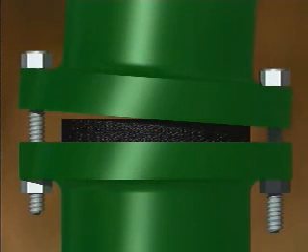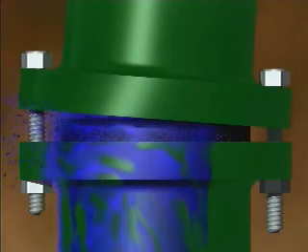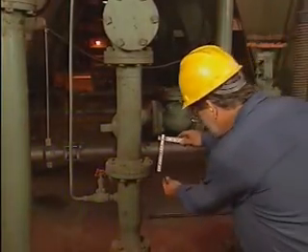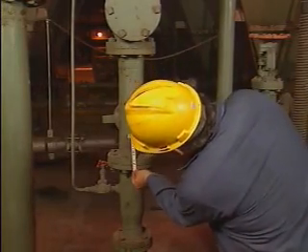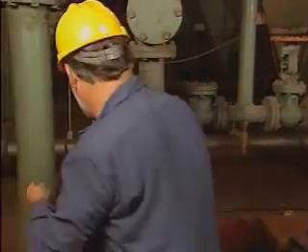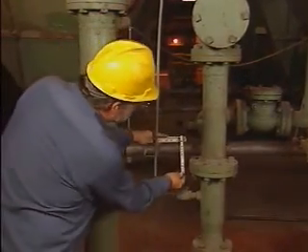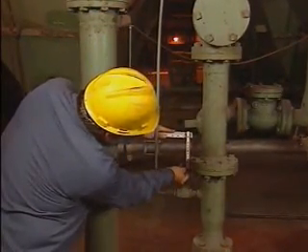If the flanges are out of alignment or the sealing surfaces are not evenly machined, the sealing surfaces may not be parallel. If the sealing surfaces are not parallel, the gasket material may not compress properly when the flanges are connected. One way to determine whether the sealing surfaces are parallel is to measure the gap between the opposing flanges at several points around the flange. If all the measurements are equal, then the sealing surfaces are parallel.